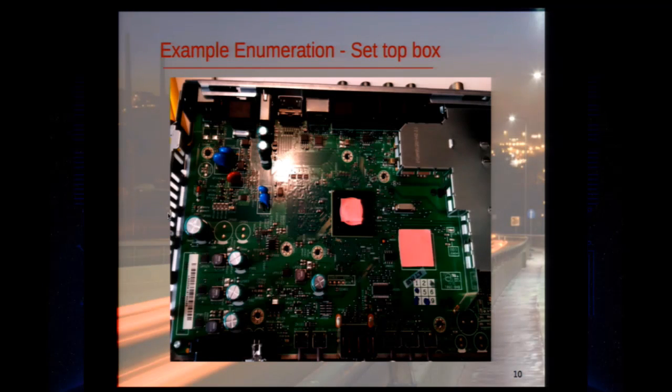And finally, we have this set-top box, which I was way more than a little ambitious when I tried to really poke at this thing. Just as an example enumeration, we have our external crystal right here on this unknown die, which would have definitely complicated things. And over right here, we have a voltage regulator, which may or may not be wise to attack on this thing, seeing as it draws about 200 milliamps from what I measured.